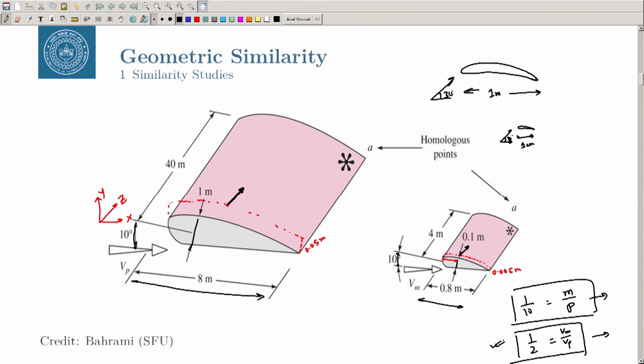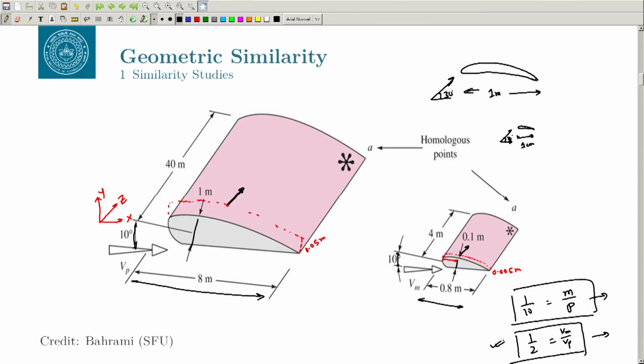And for transitional flow, particularly where the transition happens very fast, you have to be very careful whether you are talking about the laminar regime or the turbulent regime. You might have heard in your fluid mechanics course about the drag crisis, that the drag increases and suddenly the drag drops down as the regime changes, right. So, those things we need to be very careful about. Okay. Now, this is about your kinematic similarity.